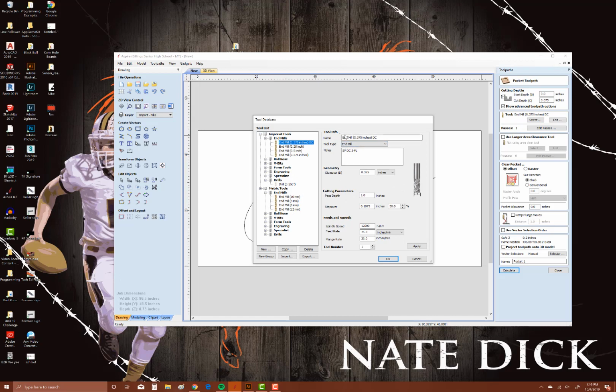With this toolpath here, the feed rates and the step over are things that I pulled in from the Amana Tool website. If you go look at the Amana Tool bits, they'll talk a little bit more about what is an appropriate feed rate, plunge rate, etc. for the tool, given the number of flutes, the depth with which you are cutting, and the speed with which you are turning the bit.